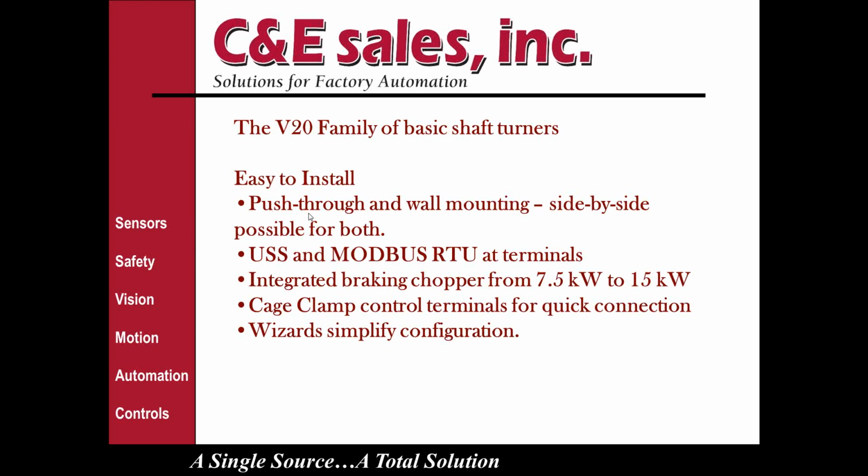A nice feature of the drive is that out of the box you can use it for push-through mounting through a hole in the back of the enclosure to ventilate heat, or you can use it for wall mounting. And it's possible to mount either one of those configurations side by side. So if you have multiple drives, you can mount them right next to each other in your enclosure, or you can push through the back and dump the heat outside the enclosure.